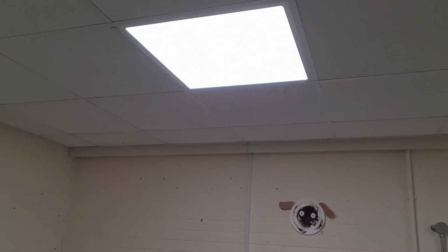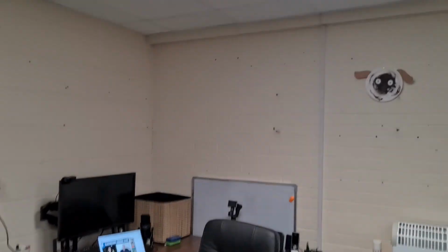I've got some of these LED lighting panels in my office space. They are on Dali controllers, so we can get all that prepped and ready as well. And ultimately the idea is to look at the differences in values we will get throughout the installation when we are doing live and dead measurements, and how the calculations that you can obtain through the dead test results can really help you with understanding what the live measurements are showing you.